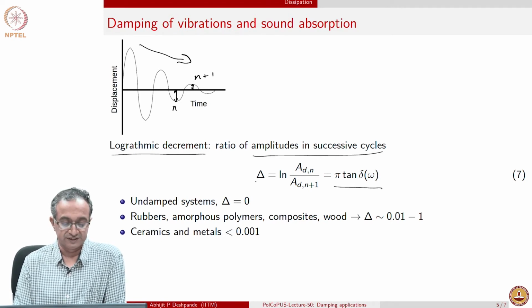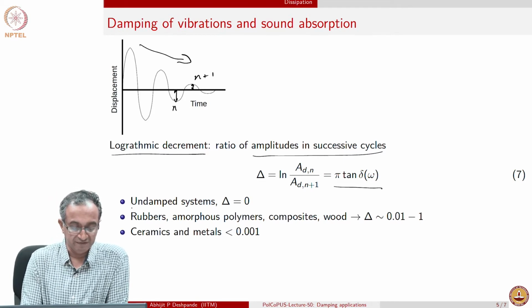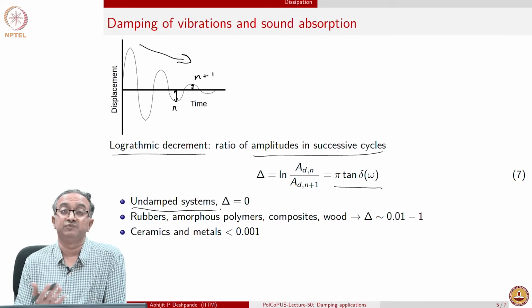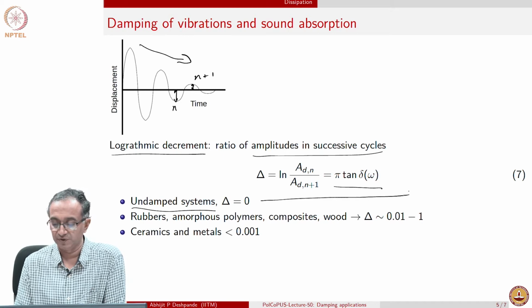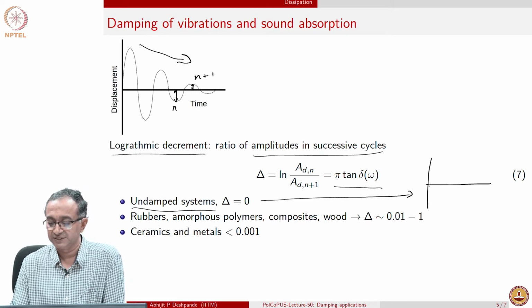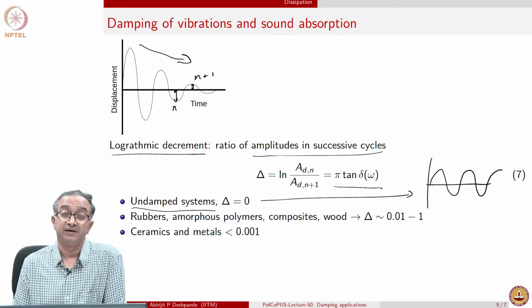So, therefore, this logarithmic decrement is what characterizes damping materials. If we have, let us say, a system which is undamped, then delta is going to be 0, and for this case of course the displacement versus time will just look like this. So, there is no change at all as a function of time; it is an undamped system.